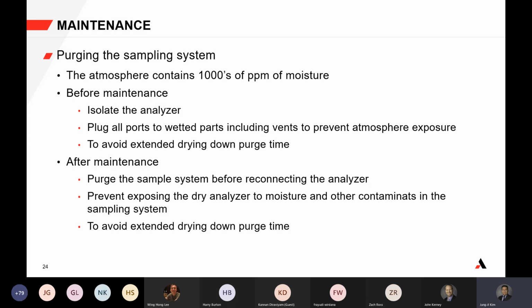So it depends on what you are using that plant nitrogen for. But if you are using it to zero an analyzer, it can be questionable, meaning it depends on the detection limit of the analyzer. So if the analyzer has a detection limit of 4 ppm, I guess it would be fine to use nitrogen that has a moisture content of 1 or 2.